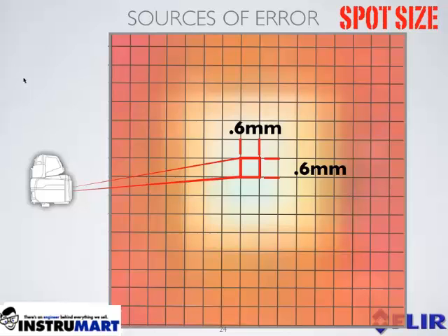Now, as a side note, as a general rule, when using an IR camera to sample targets, it is recommended to use a camera-lens combination that will maintain a distance to the target that allows a 3 by 3 pixel sampling. Now, why is this? Well, this ensures we will capture at least 1 pixel squarely on our target. And if we have at least 1 pixel, we can measure it accurately.